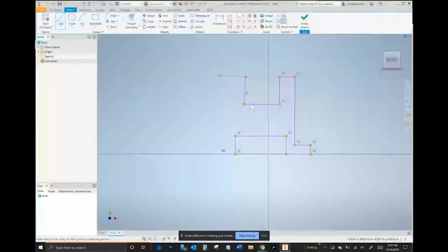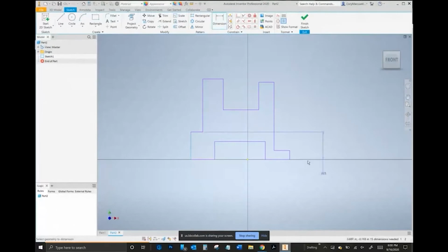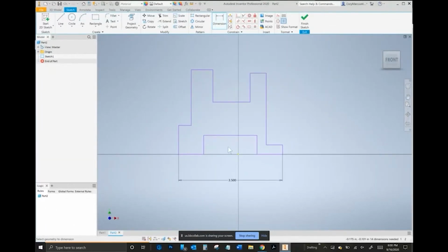And as you can see, it did mess up and not stick at a perpendicular or vertical alignment. So I'm going to go ahead and fix my goof. And I'll make sure to snap where this one does and where this one does. Okay, so let's slap in this overall width so it controls everything, because it's going to grow 3 times the size.